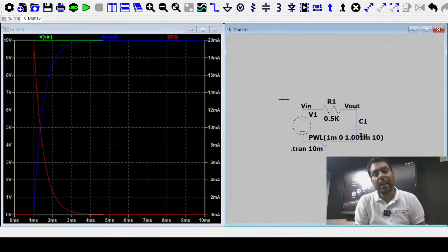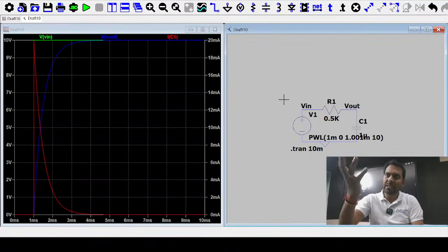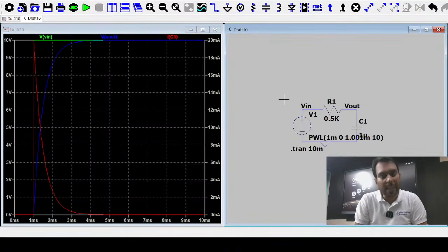Okay, so in a layout you will find that metal has a sheet resistance, and metal has fringe capacitance, and you have a clock. Of course, these resistors or capacitors are not physically present in your circuit, but by post layout simulation you will find that the metal has a resistance, that is sheet resistance, and metal will have a parasitic capacitance between two metals parallel to each other, with C is equal to epsilon A by D. So you have a resistance and also a capacitor. So this is an unwanted effect in your circuit.